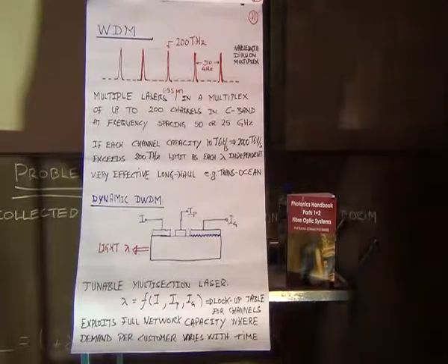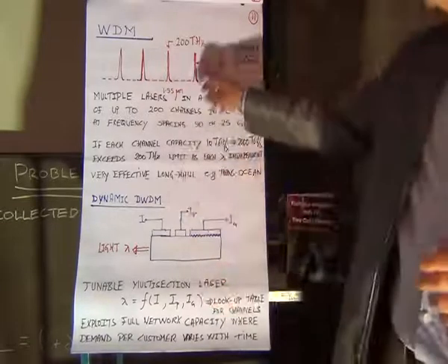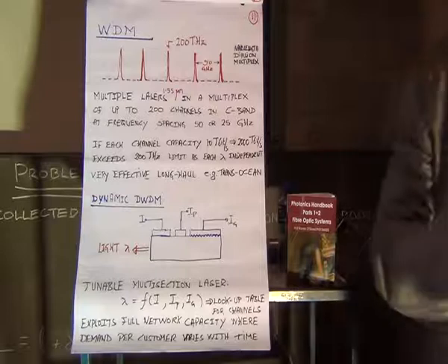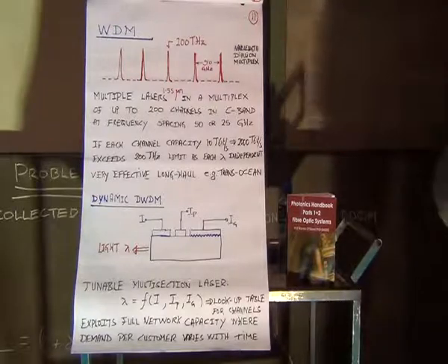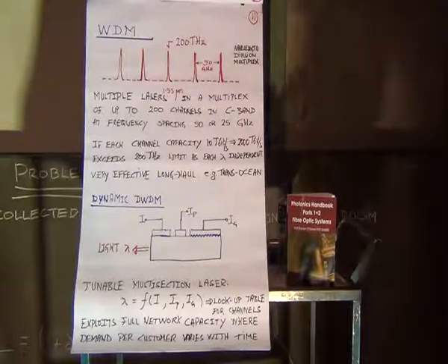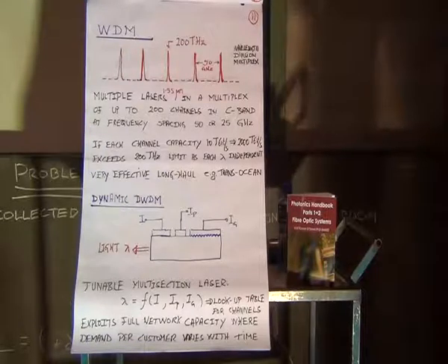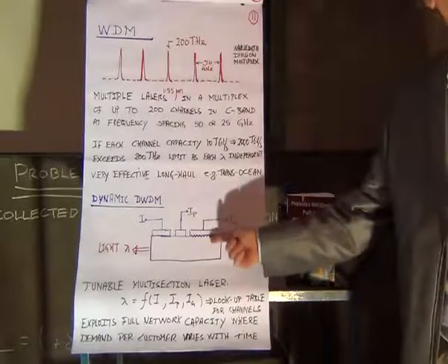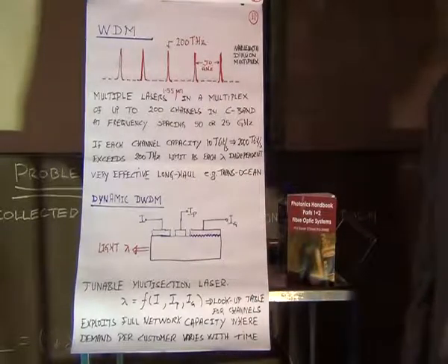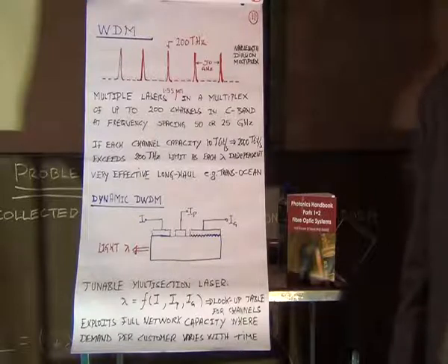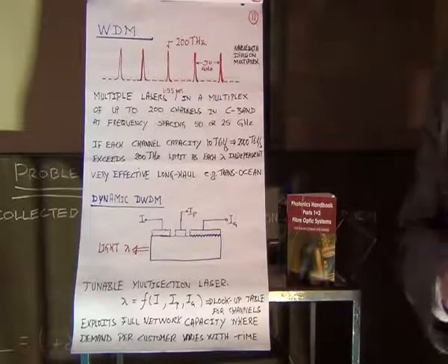For the duration of the IP packet, you tune to a particular wavelength, and then your fibre Bragg gratings at all the nodes in your network will reflect some of the channels and transmit the others totally passively without you doing anything. All you had to do was select the wavelength of the IP packet at the beginning. The wavelength is the address. And it's all happening dynamically.